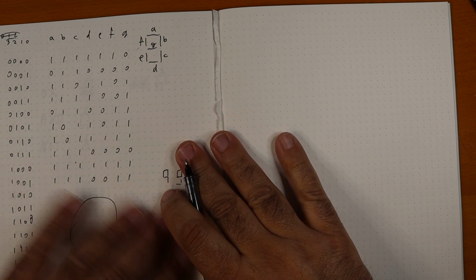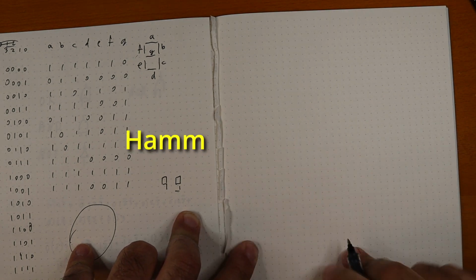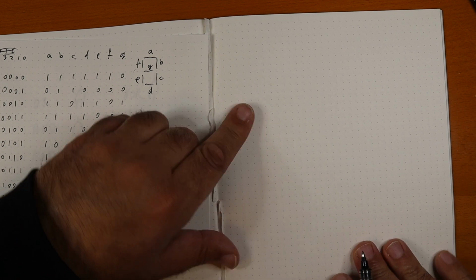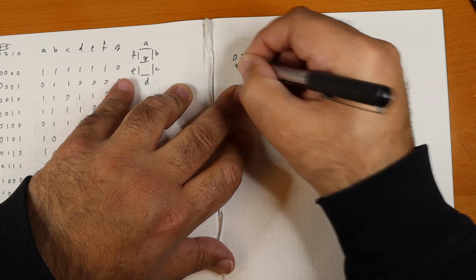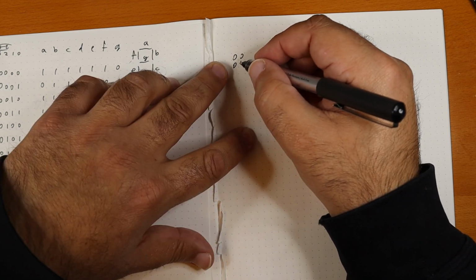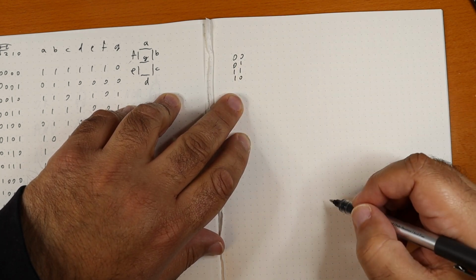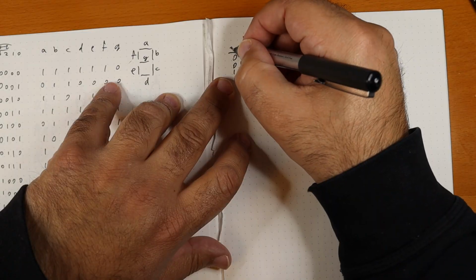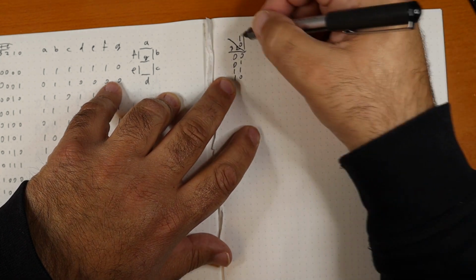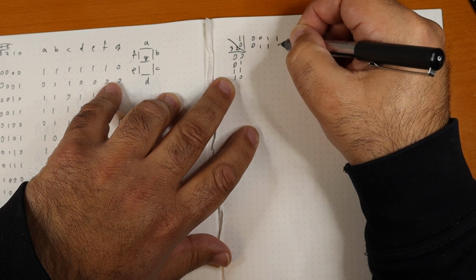So we take all of our inputs and we write them out as cells that have Hamming distance of 1. Hamming distance is the number of bits that change between two numbers. So we can go 0, 0, 0, 1. And now the next number needs to be 1 bit different than this. So it will be 1, 1, and then 1, 0. And we'll call this 3 and 2 inputs. The 1 and 0 inputs will do the same. So we'll go 0, 0, 0, 1, 1, 1, 1, 0.